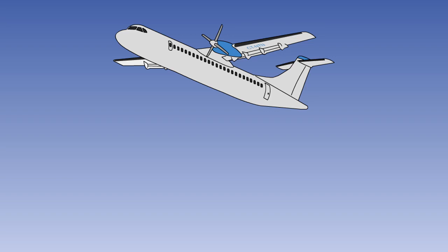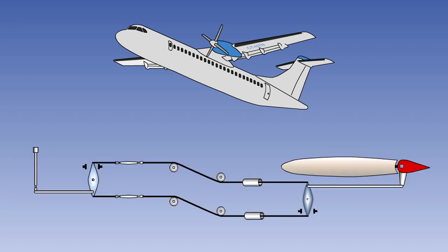In this lesson, we will discuss manual operation of the primary flight controls. The movement of the flying control surfaces, in response to the movement of the cockpit controls, may be achieved manually on smaller aircraft. In a manual system, the control surfaces are connected directly to the cockpit controls by a system of cables, rods, levers and chains.